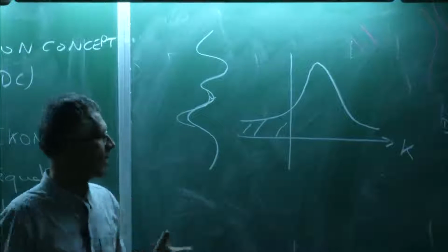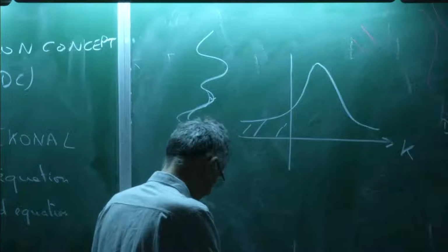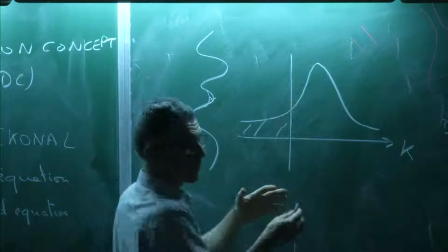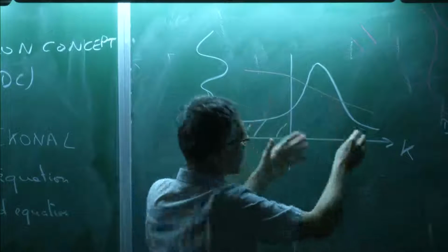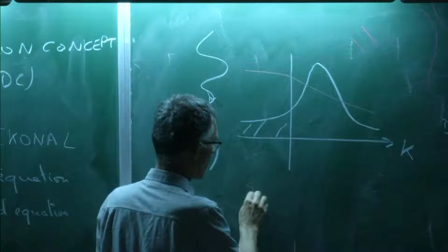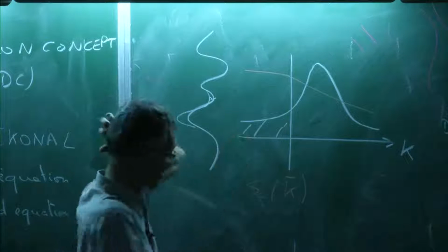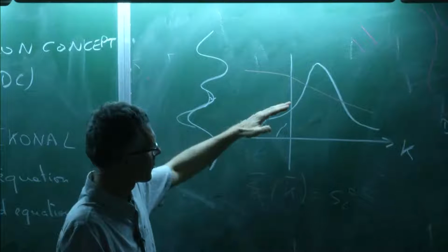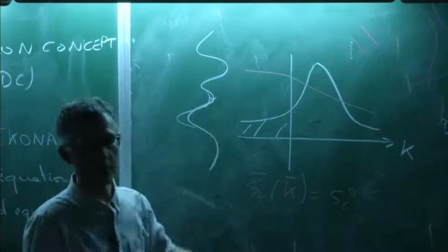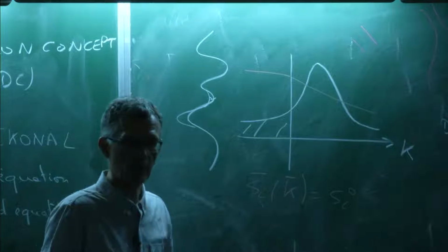So it looks like all the flames are turning themselves so that they always prefer to be stretched rather than compressed. Which really means that if you want to incorporate the effect of stretch on the local consumption speed, it's kind of difficult, because those flames depend on the Lewis number, but typically those flames will burn more and those will burn less, or the other way, and you average that. And so again, you need to find a model for SL of the mean stretch. You might know the SL of the local stretch, but what you want is the mean, and that's difficult. So in many cases, what we end up doing is to say there is no effect. This is SL0, because in the DNS, what we see most often is that the average SC is maybe 20% off from the consumption speed, so we don't change it. But there might be cases where it's not true.